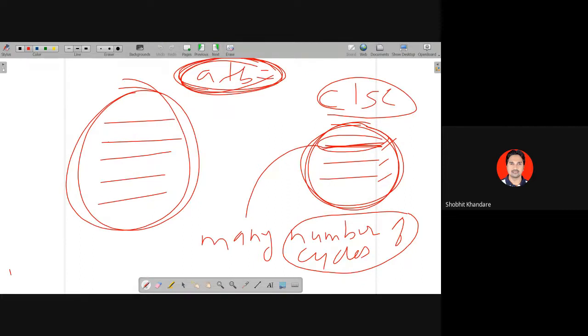Okay. Now come to this one. So in the CISC, I have told you that in this you will be having less instructions to carry out the same program, but here the number of cycles would be more. The CISC architecture will have complex instruction set where the task can be performed with the minimum number of instructions, but to perform the same program, the number of cycles per instruction would be more.